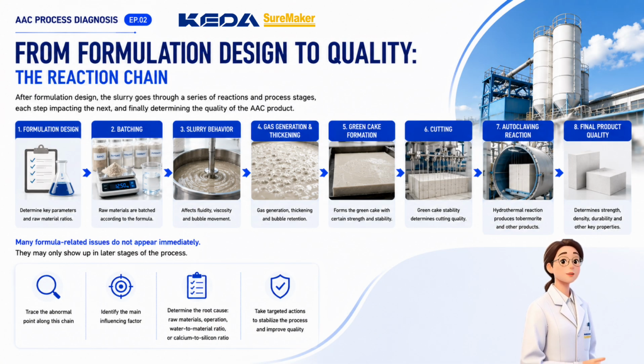First, we need to establish a diagnosis chain. After formula design is completed, raw materials enter the batching stage. Batching determines slurry behavior. Then the slurry begins gas generation, thickening, and hardening, forming the green cake. Green cake stability determines cutting quality. Finally, it affects the autoclaving reaction and the quality of the finished product. This chain is very important. Many formula-related problems cannot be directly observed during batching. Instead, they appear in later process stages.